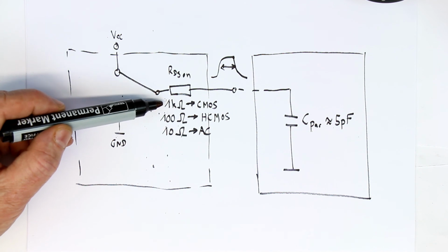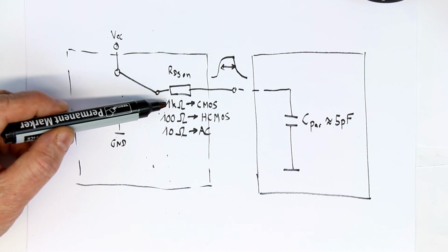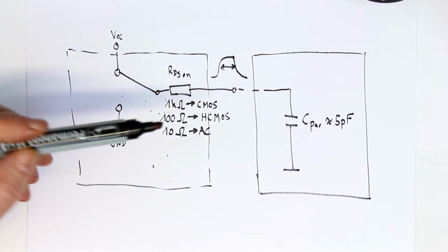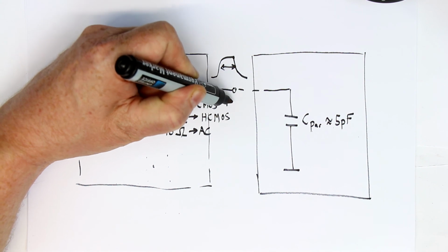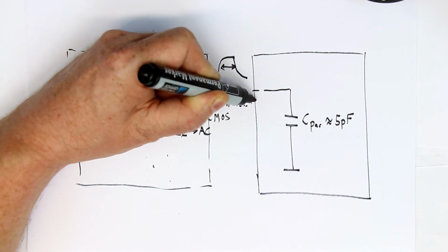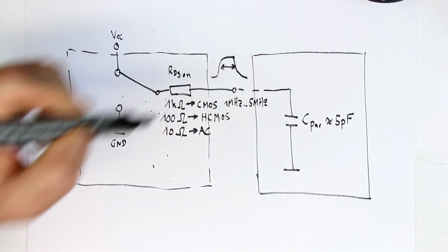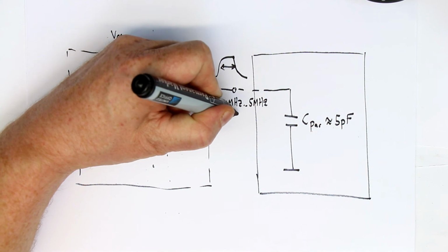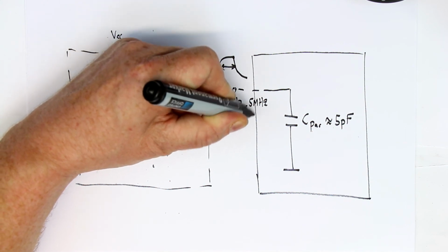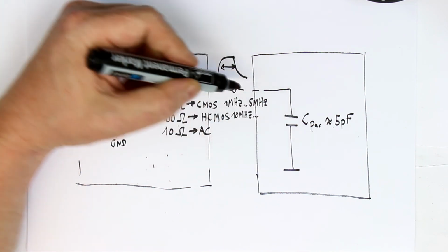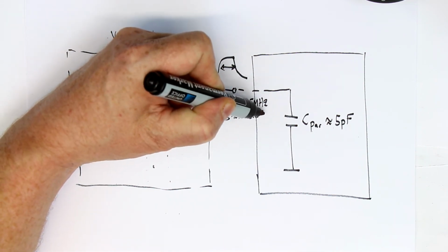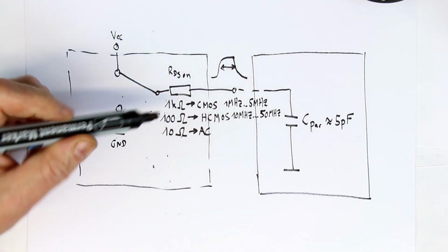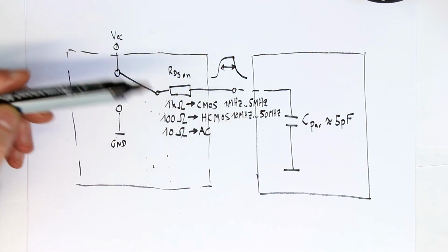For example, the NXP series is the fastest CMOS series, the HEF series. There you have speeds in the range 1 megahertz up to around 5 megahertz. Some gates even go to 10 megahertz or so. In HC CMOS, you're much faster, around a factor of 10, depending on the type of IC you get. It's between 10 and, I don't know if it goes up to 50 megahertz, but it could be that some simple logic gates go even to 50 megahertz.